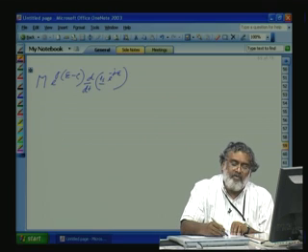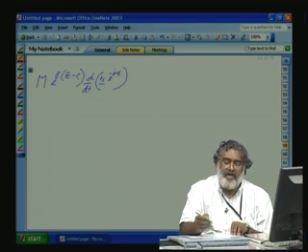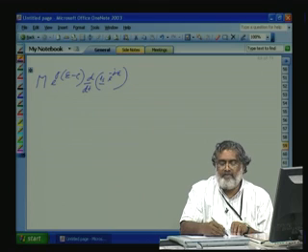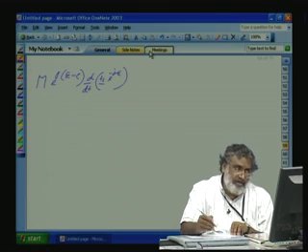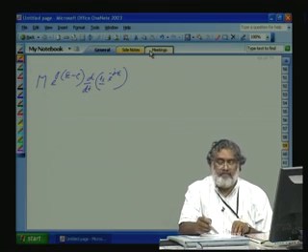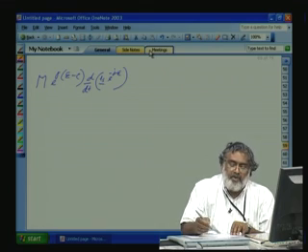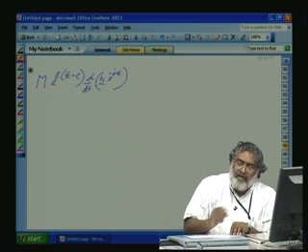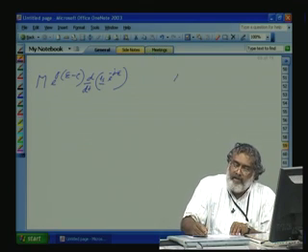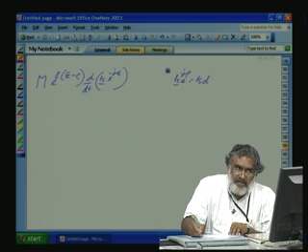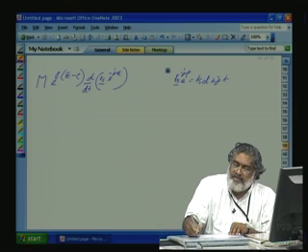So, that is why we have multiplied by e raised to j epsilon, and then again multiplying by e raised to minus j rho, we are bringing it to the dq axis. So, here also we know e raised to j epsilon, e raised to minus j rho is equal to ISD plus j ISQ.